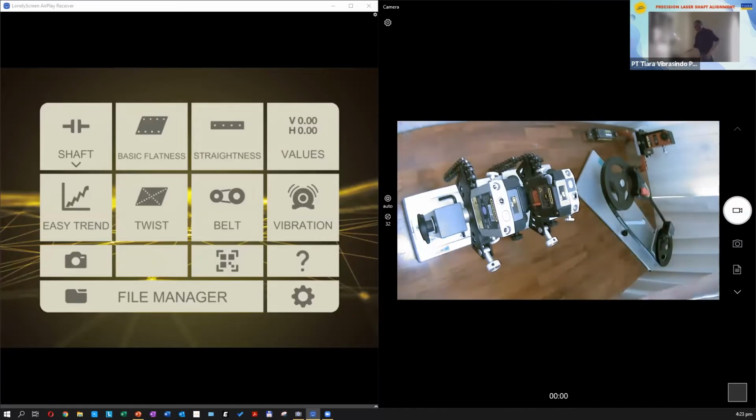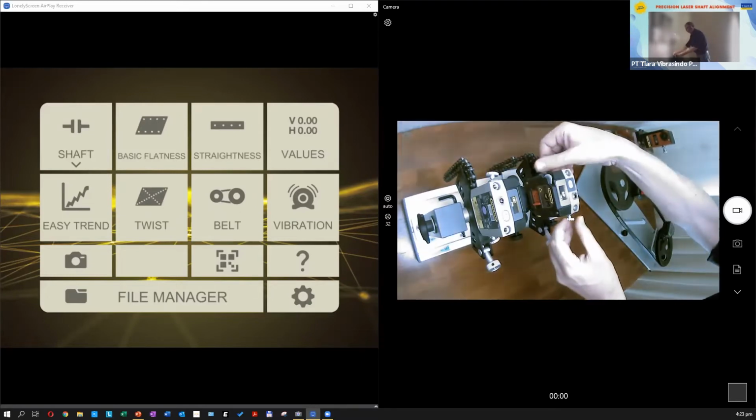I have here a very small demonstration rig where, on the left-hand side, I have my stationary machine. That's typically the part of the machine combination that is my reference, which is non-movable. Towards this reference, I'm adjusting the position of the machine on the right-hand side. So the right measurement unit, I'm considering as the movable machine. I'm doing the correction on the right machine only, in vertical direction and in horizontal direction.